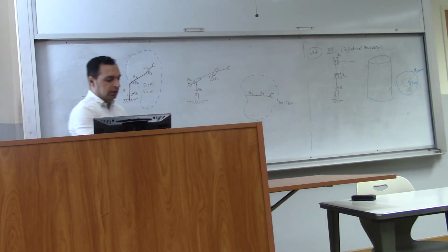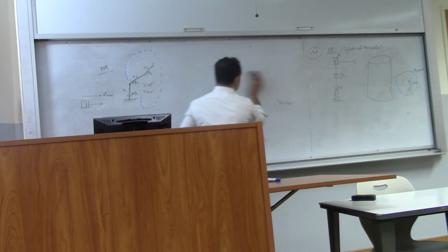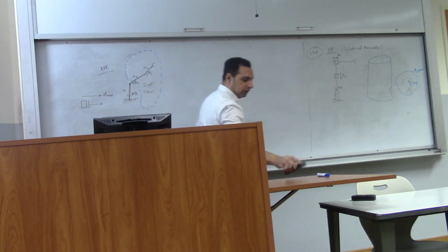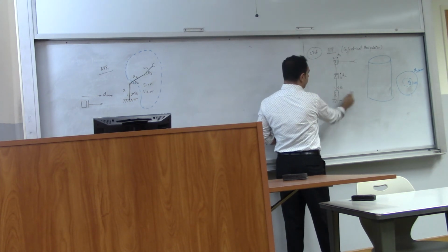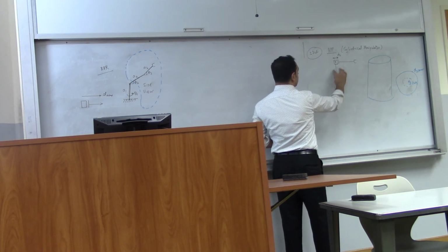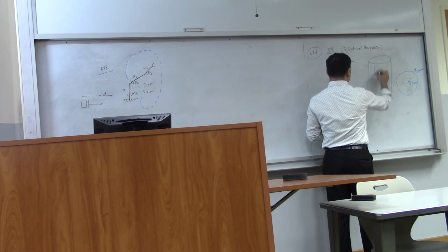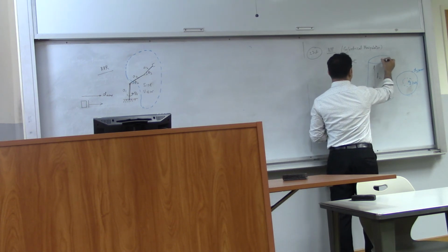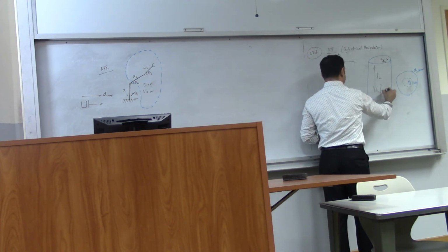All right. So all you have to do is imagine the motion of each of the joints. This will generate a circular motion because you're assuming this to be fully revolute. This will generate a motion. This will be the length of this. This will be due to motion of D2 up and down. This will be D3. Okay, and the motion along this is due to theta 1.